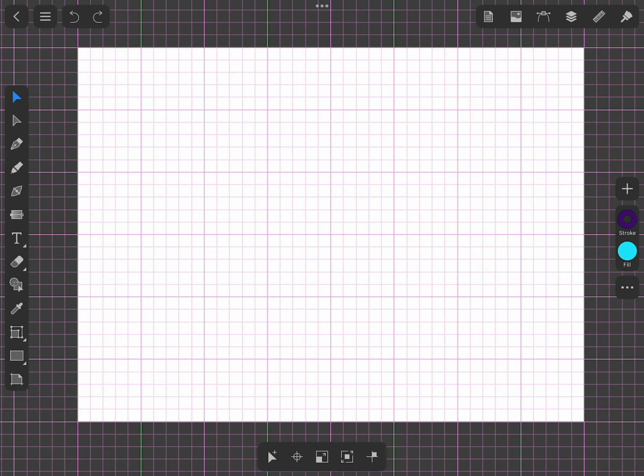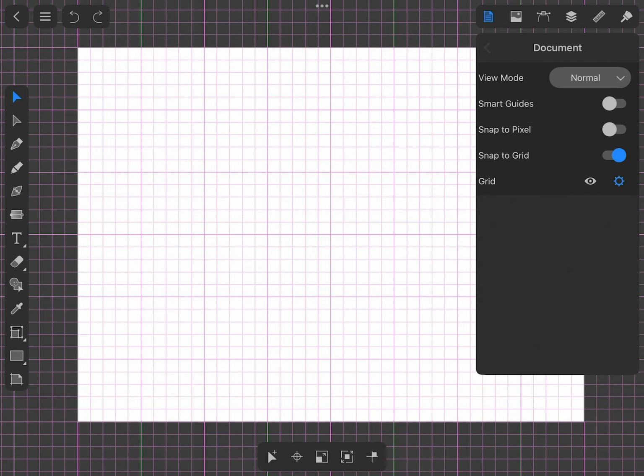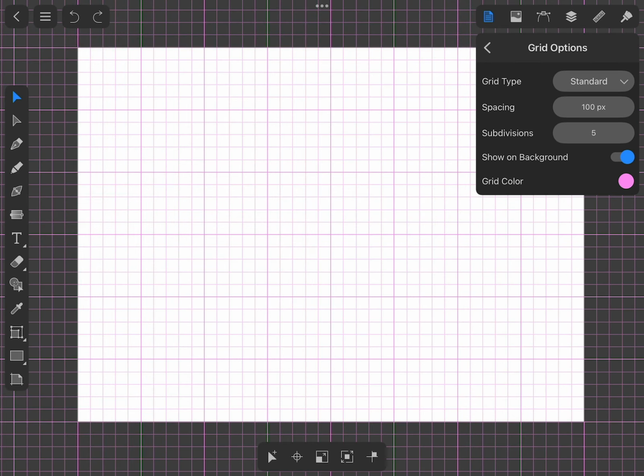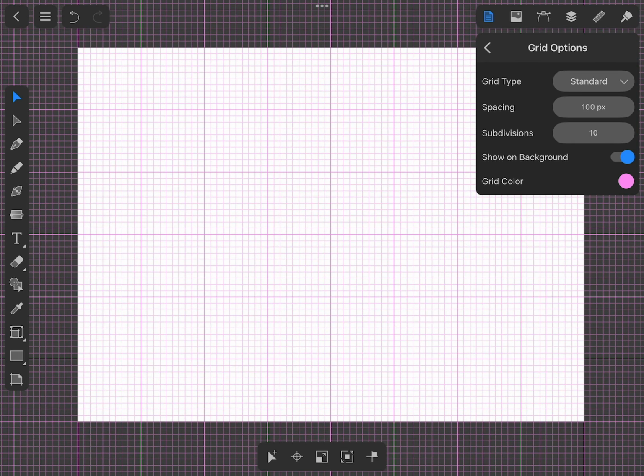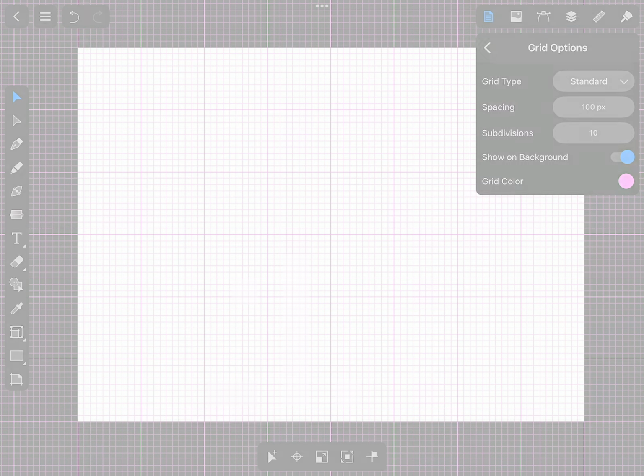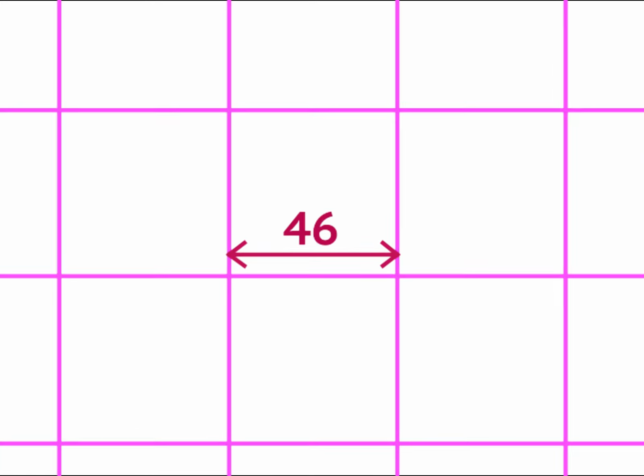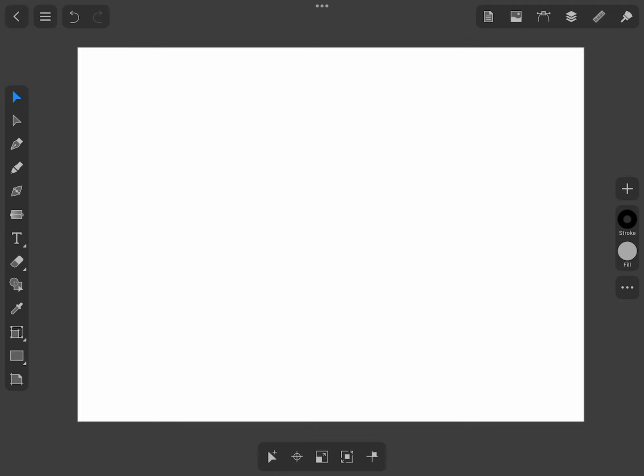You can control the depth and dimensionality of your design by adjusting the step and subdivisions to make your design journey even more convenient. The step is the space between the 2 lines in the grid. The subdivision is the number of squares in a bigger square. Now we move on to using the isometric grid. Usually designers will use it for creating a visual 3D effect on a 2-dimensional design.